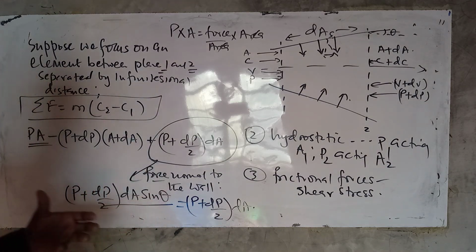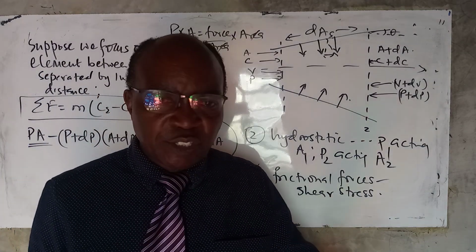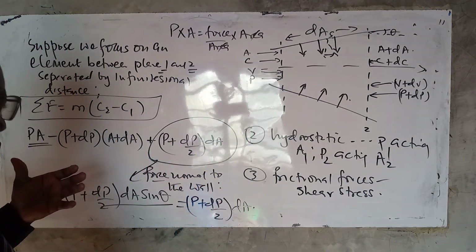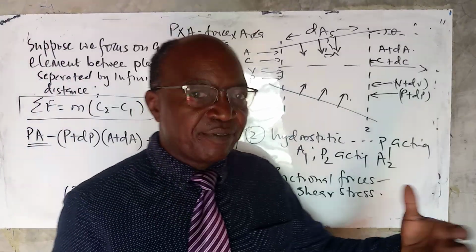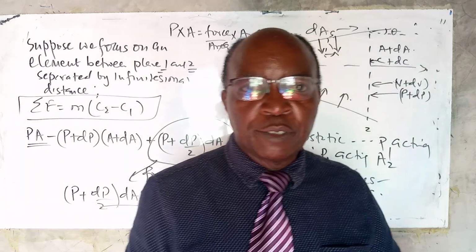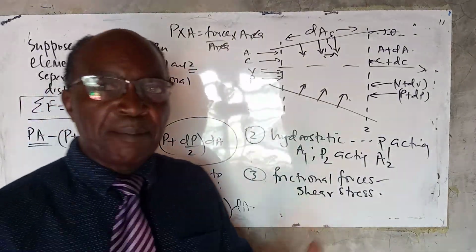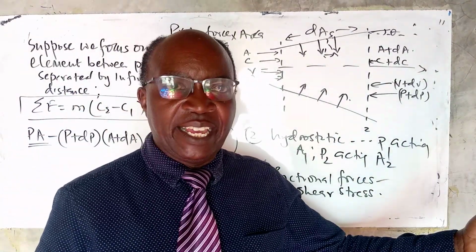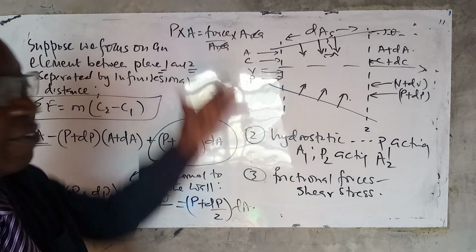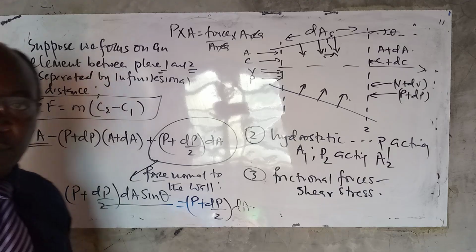And we are not going to focus on frictional forces, because for us to assume a one-dimensional steady flow, we will not want to assume that frictional forces are exaggerated in this flow, because it will lead to non-uniformity in the flow. If you consider, for example, the frictional forces between the layers, then there will be no uniformity in the properties on the face of that fluid which is perpendicular to the flow.